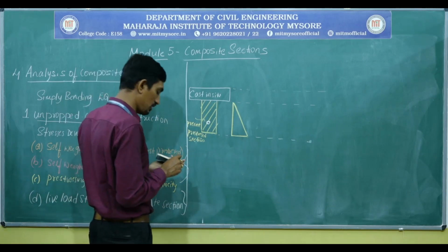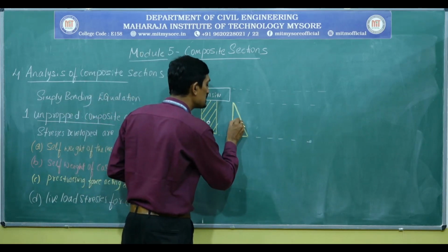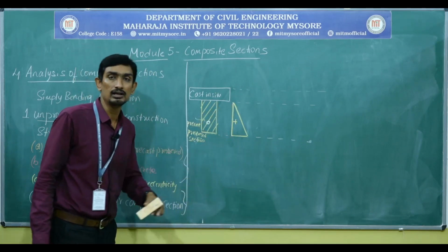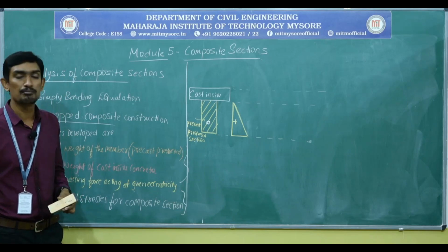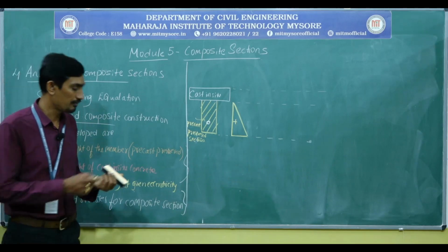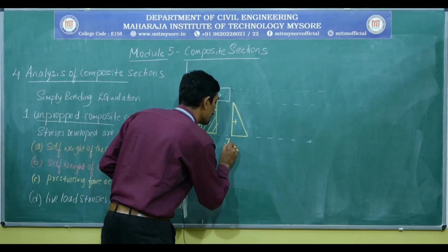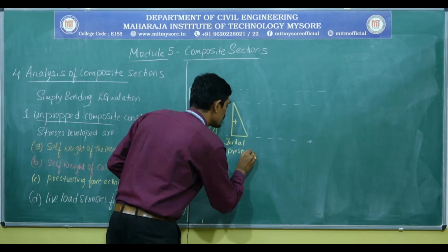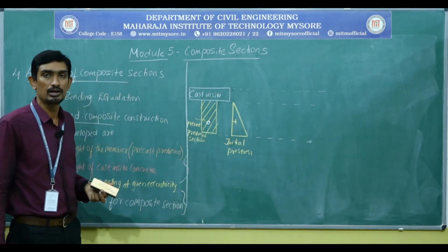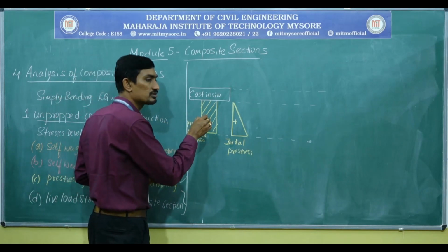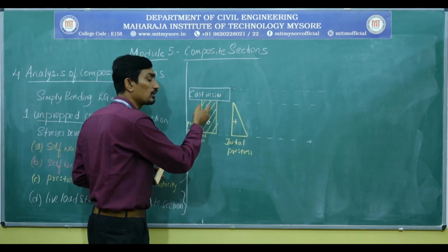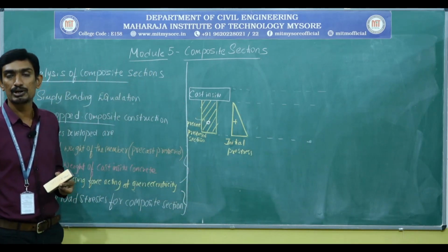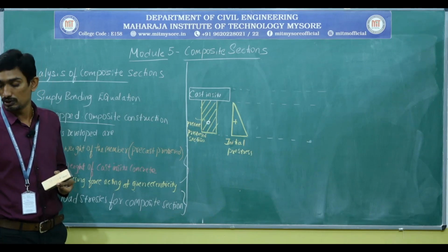Because of this, it will develop the initial pre-stress, which is 0 at the top, and it will be compressive in nature, which is called initial pre-stress. So these stresses will be developed due to the pre-stressing force induced in the precast pre-stressed unit.